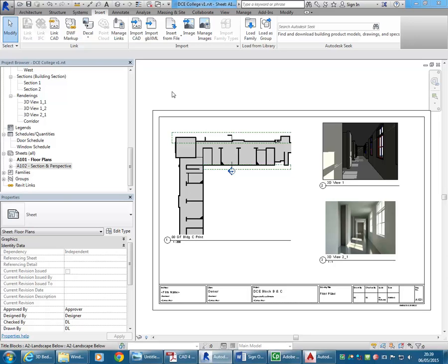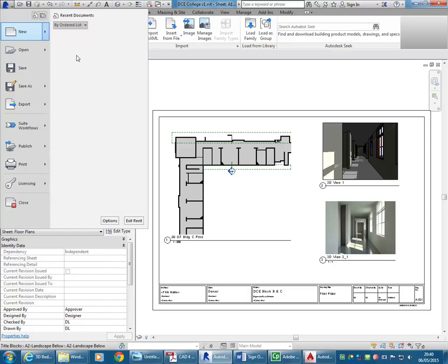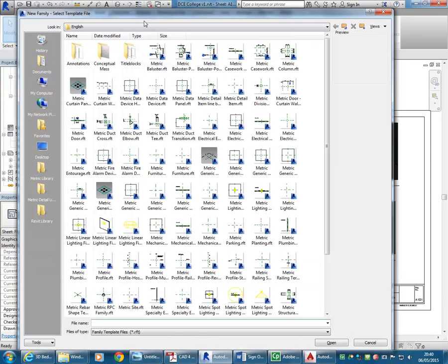And so the way to bring it into Revit is, for things like this, always make a new family. So you don't want to be trying to manage that in a project. It's just too much work, and you've got to do it again if you want to use the file again. So here you could use furniture, but it's probably better to use casework, and then later on you could have it showing as being cut.